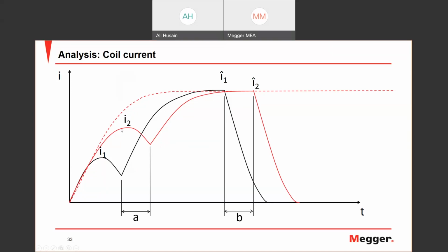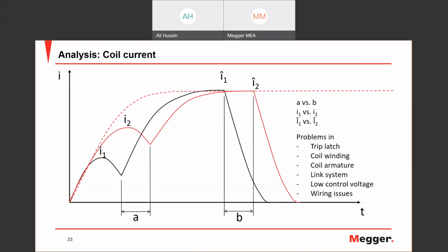This means you have a bad lubrication not in your mechanism of the breaker, but in your control circuitry or in your coil itself. So you maybe need to check that and lubricate it correctly. This is information that can only be given by the first trip test. If you have any problem in that, you can see it here.